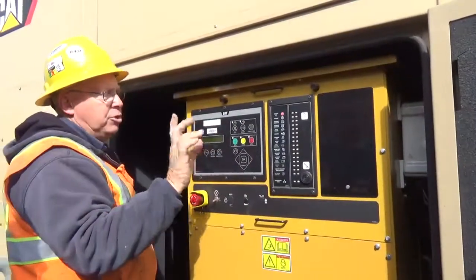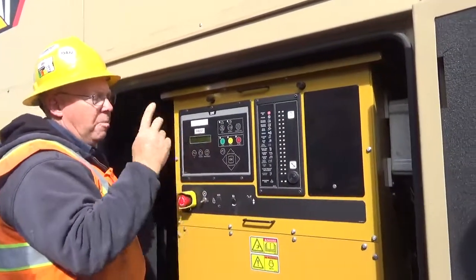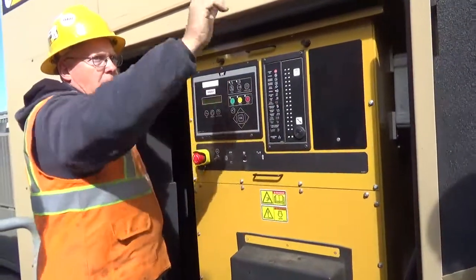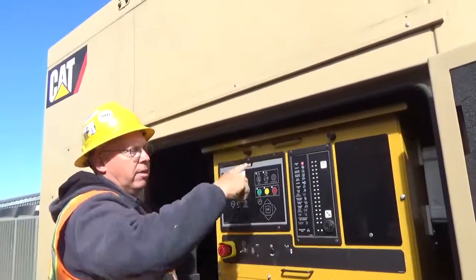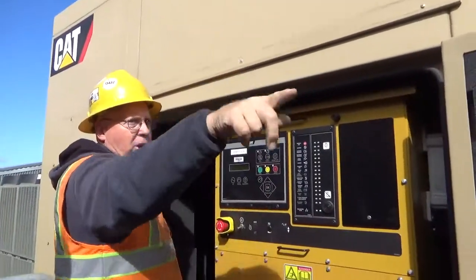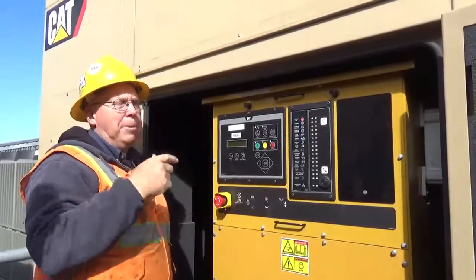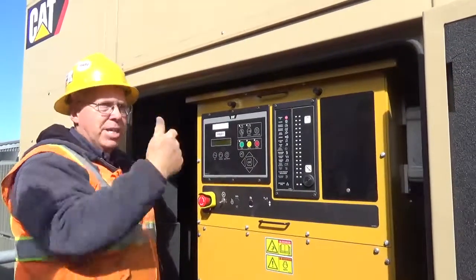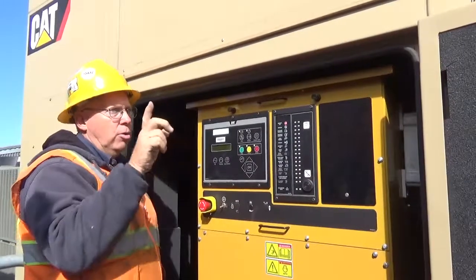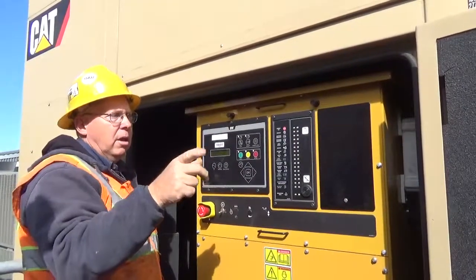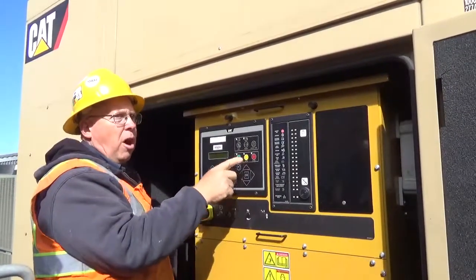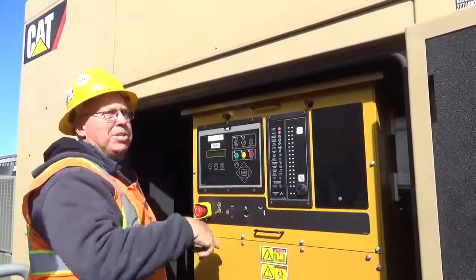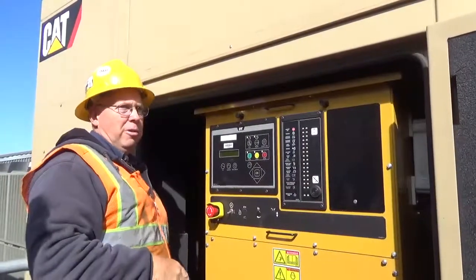Now, if he's generating it, you may have to do it twice. So you may have to go to off reset, clear, go to him, clear, then come back, put this in auto, then go put him in auto. Because what happens is, I'm sending him a signal that I was shut down. He is in turn sending it back to me again. So you have to make sure he's clear before you go to auto, because as soon as you go to auto, you still got one coming from him, because you haven't cleared it. So it's going to trip this again, and then you got to start the whole process over.